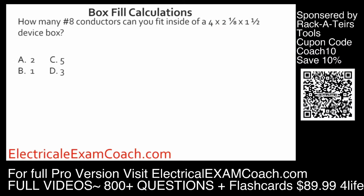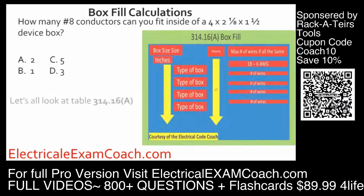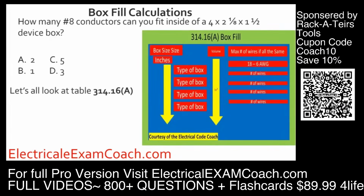How many number 8 conductors can you fit inside of a 4 by 2 1/8 by 1.5 device box? We head to 314.16(A). We're going to find our gauge wire. Then we're going to come over and find our type of box and size, make sure we do everything correctly, and we're going to find that it holds 3.